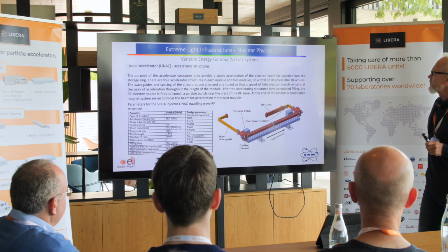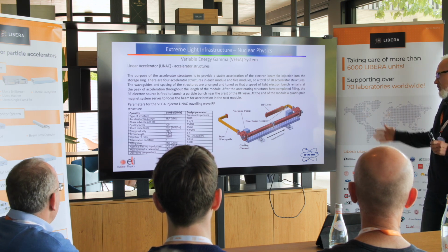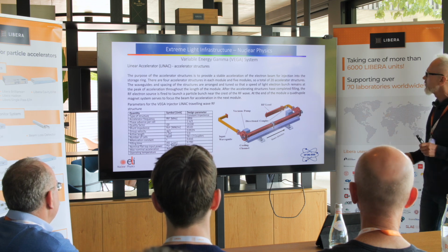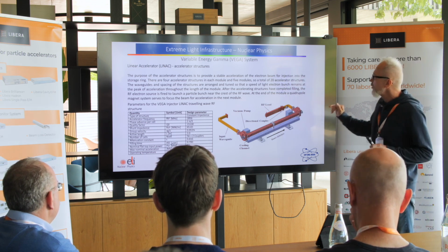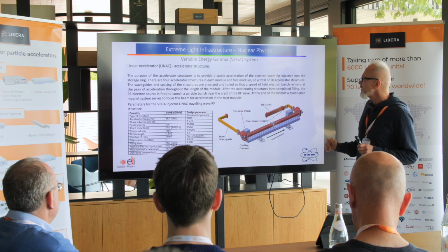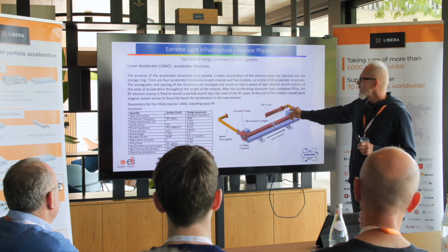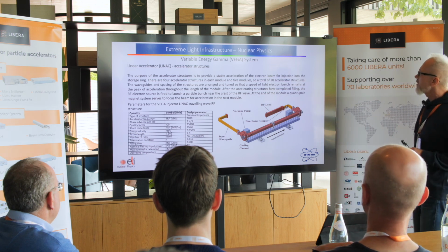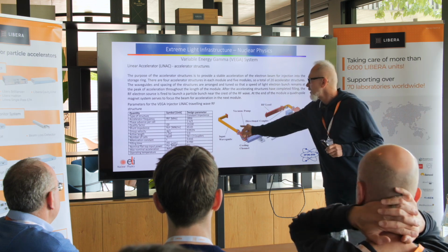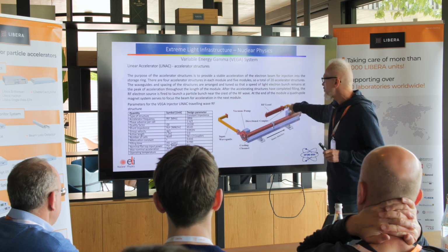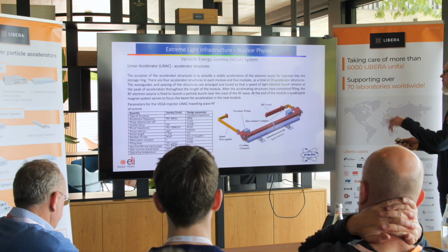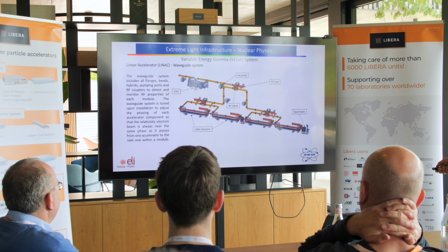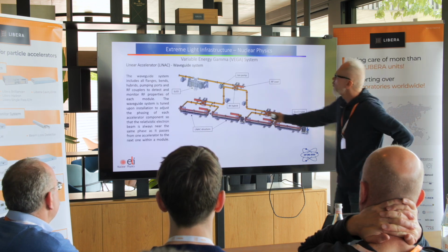And this could be done, as I will explain further, with low-level RF equipment. Also, we need low-level RF equipment in order to analyze the forward and reverse pulse. And we have some couplers at the input and the output of each structure, but I will give you more details later. So this is the whole module,